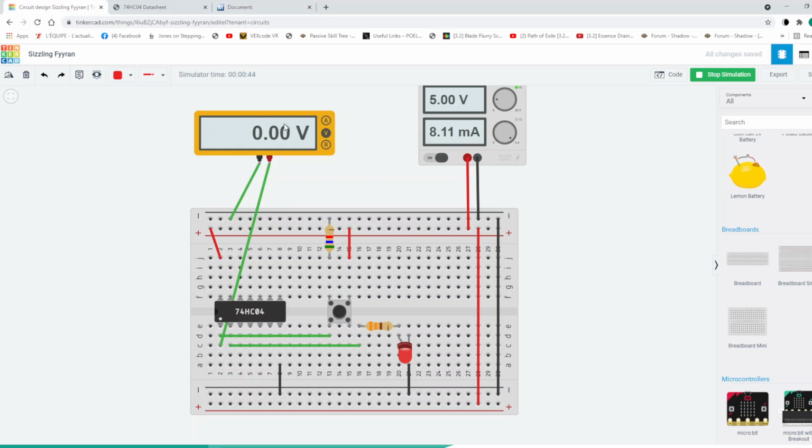Okay, so you see that this is indeed inverting the signal. If the input signal right now is 0 volt, the LED is on. That means it's receiving 5 volt. And if the input is 5 volt, we can see that the LED is off, hence the term inverter. But what I want to show you is this. Right here, I see an input voltage of 5 volts, okay? And my LED is on, everything is okay.